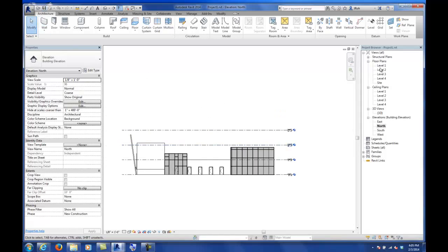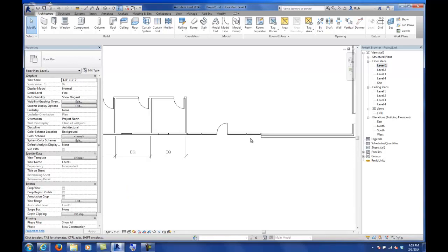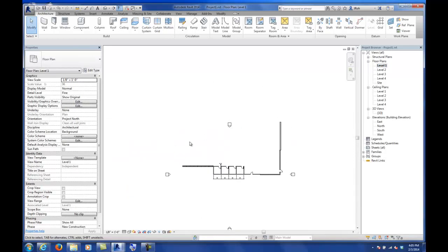Let's go ahead and draw on the level 1 floor plan. And we've got kind of something to draw around. We've been drawing this little bit of a boundary here. The floor command and roof command and all your horizontal assemblies are right here. There's roof, ceiling, and floor. It's in the architecture tab, and it's right after components and columns and so on.